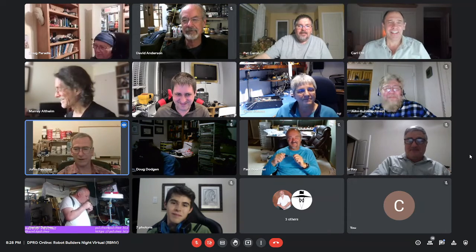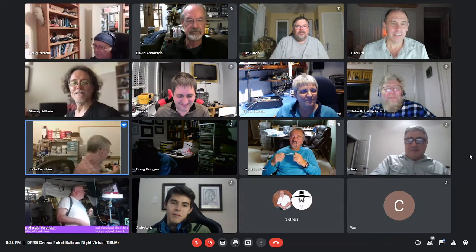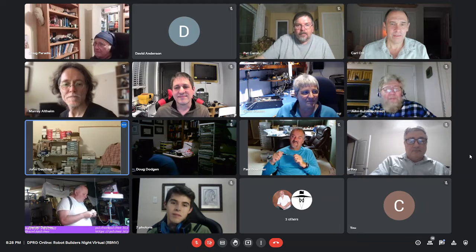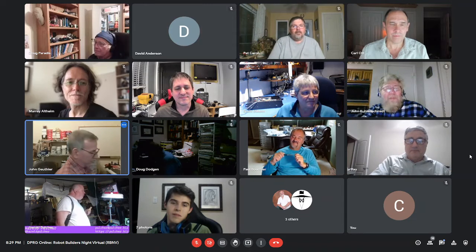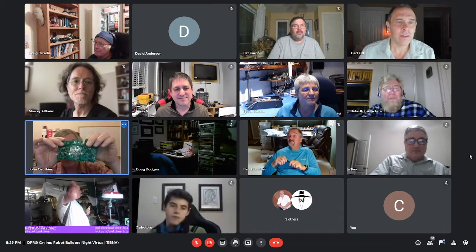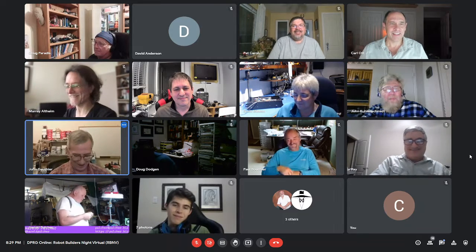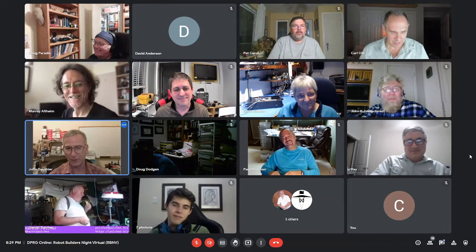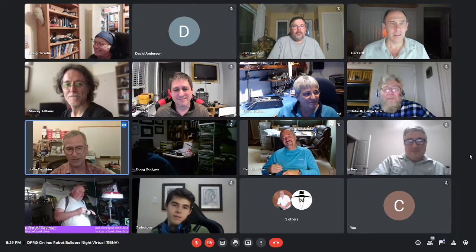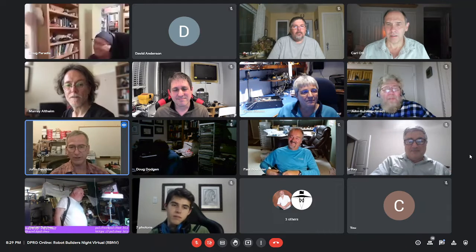Oh, and our collaborative motor controller project is taking a different turn. I assembled 3 of these boards using my EasyMake reflow oven, and all 3 of them fail in different ways. So I'm convinced that these little tiny QFN parts, with the exceptionally small pins, are the problem. It's just impossible to get them placed without creating solder bridges that you can't get to.